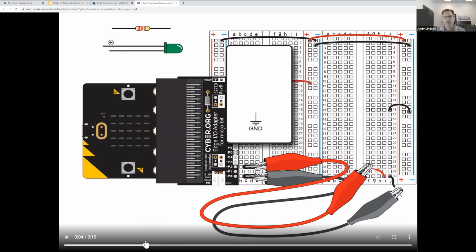And then the next part over here is the resistor, and it's going to move over to the breadboard. No, I'm sorry, that's right, the LED. The LED goes first. So here's our little light. And so it gets plugged into the breadboard, and you can see the little plus here, and that actually corresponds with this little line. It's a one-way valve, and so current can only flow through it one way. If you get it backwards, nothing bad happens, it just won't turn on.